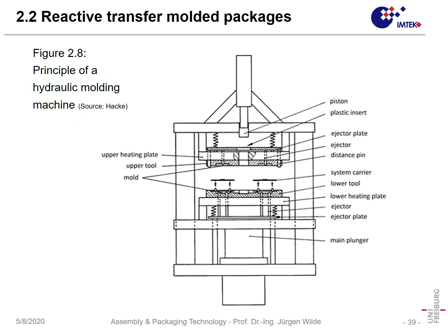Here is again a cross-section of that machine. We can see here the cavity. Here are the so-called system carriers. That's the lead frames with the chips. They are put in. Of course, you cannot put them in by hand in a tool that is 180 degrees centigrade hot, but these are pre-arranged on some magazine, and that magazine is fed. So you feed them all together in, and then this waffle iron is closing.